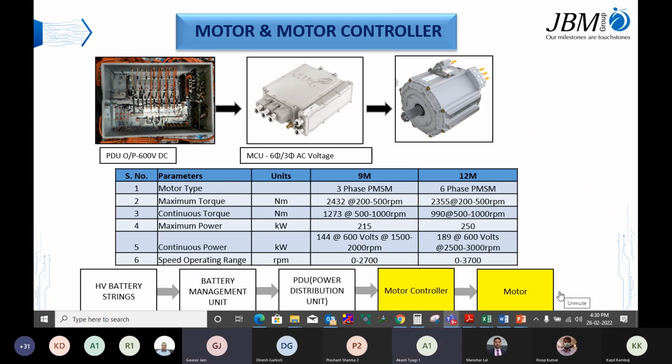Sir, as far as I can understand, regarding the motor selection, we are just going for the maximum torque, and for the maximum speed we are using the RPM, and we are looking at the gear ratio whether we can achieve both of these things.